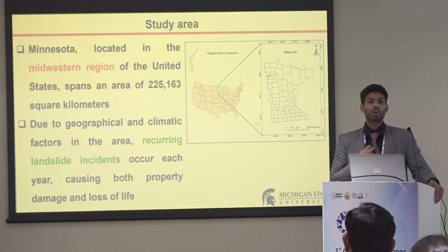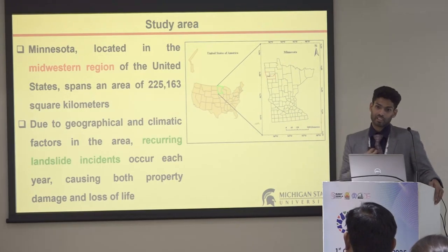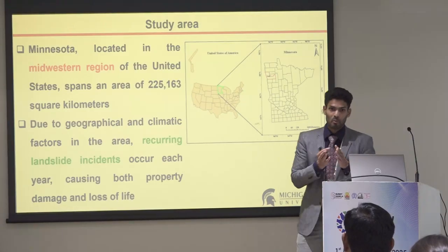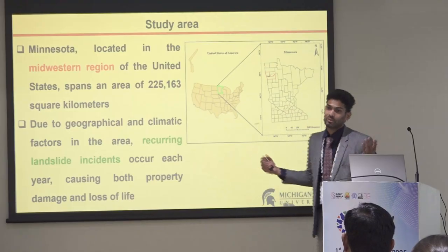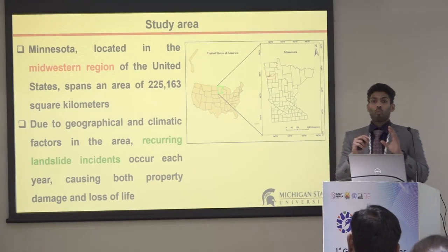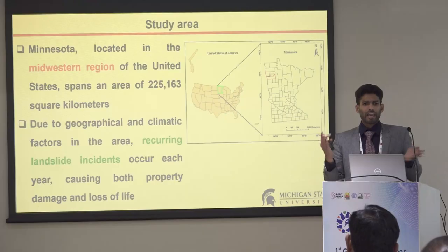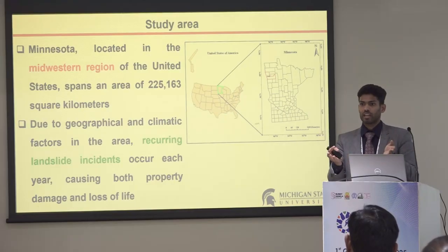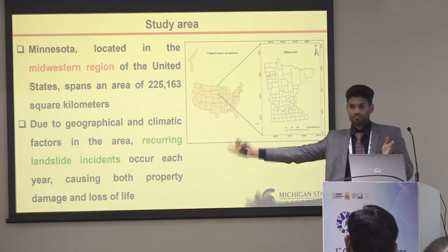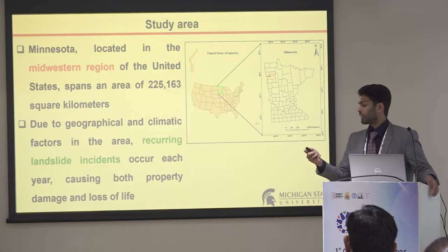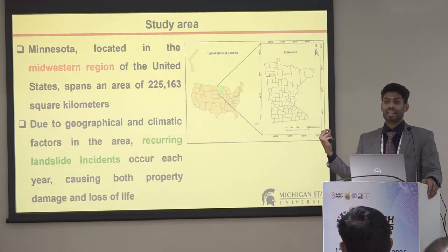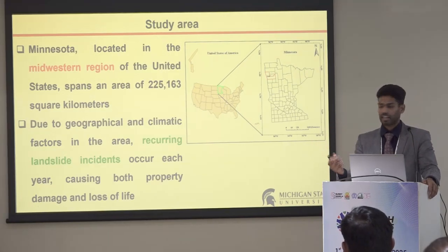I can also vouch for it because I lived there. I've tested both Indian plus 45 and Minnesota minus 45. Anyway, why am I even saying that? If the same soil is subjected to both extremes, then you'll see the cracking and desiccation behavior. I'll also show you the tension cracks that happen, especially if it is a high PI clay.